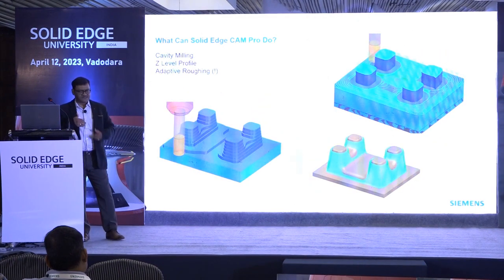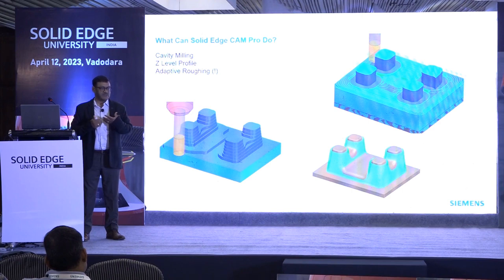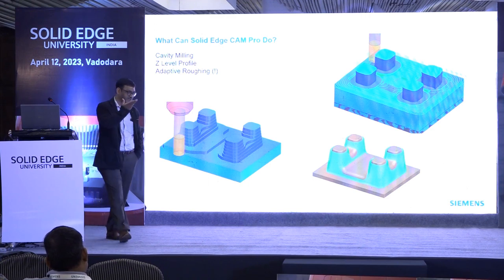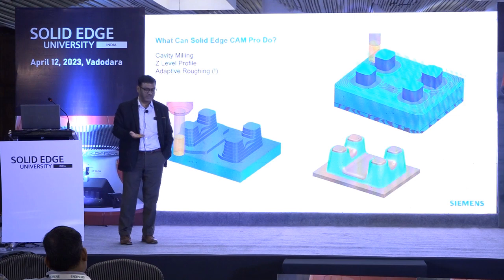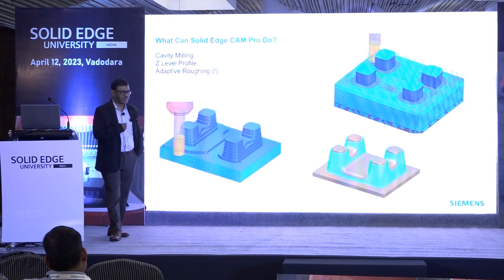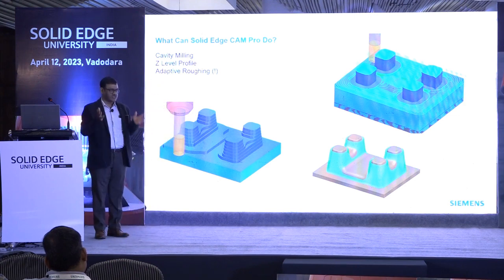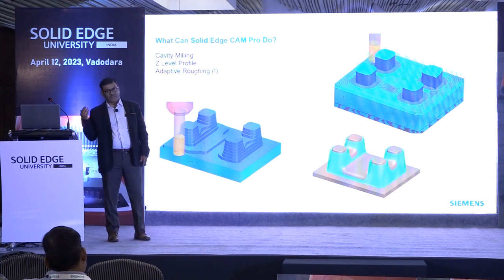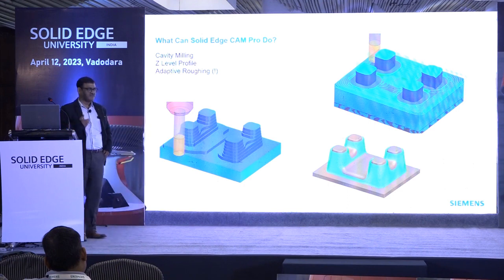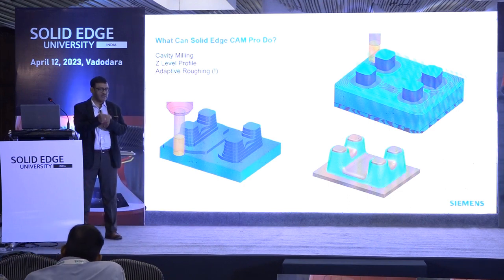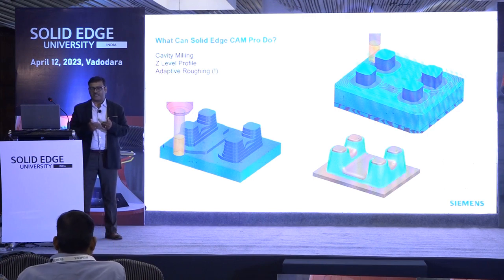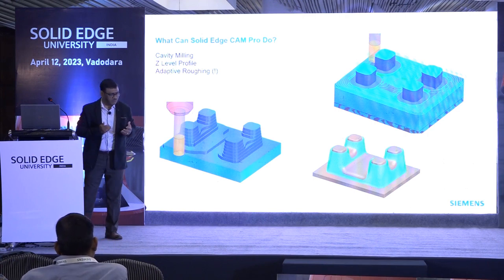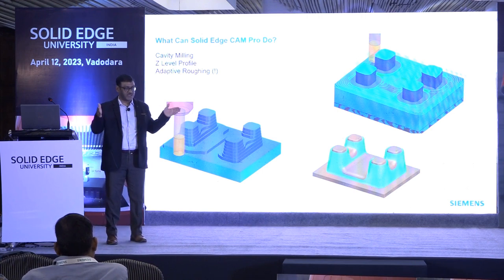Now, you may say, if I am a mold and die customer, right? Normally, prismatic parts are simple, right? There are facing and hole making and all that, simple parts that an operator himself can do on the machine. But normally, we suggest you go with a model-based approach, meaning the model should be the master. You generate the program. Once you do this in 3D, then you can get into model automation, right? That's where otherwise we will never reach the automation that is planned. You may do a wonderful automation in the design, that is well, because you're reducing your design time.